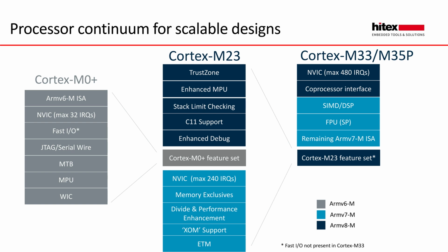To construct that type of project, the best way to create these partitions is to have two separate projects. We create one for the secure world and one for the non-secure world. If we think back to the very first week, we discussed creating a bootloader and main application code, and this follows exactly those principles.